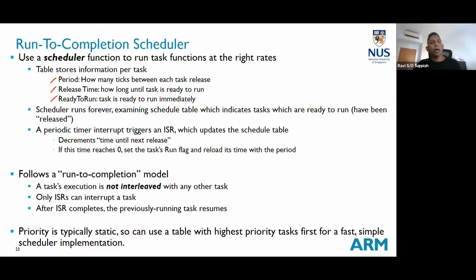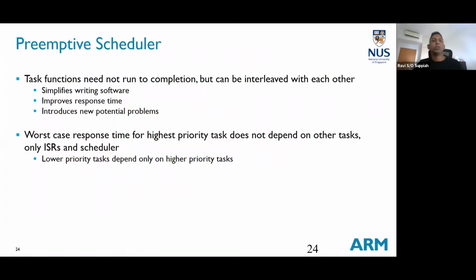The next alternative, which is better, is to go directly towards using a preemptive scheduler. And a preemptive scheduler is basically the bedrock of your RTOS. When you use an RTOS, you are already making use of a framework that allows this preemptive scheduling. More importantly, preemptive scheduling brings a lot of other challenges as well, in terms of race conditions, data integrity, how to make different tasks talk to each other, and so on. All of this is already encompassed within the RTOS.